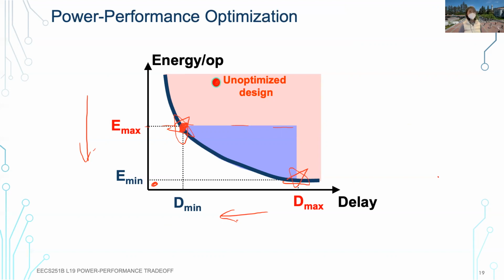For most hardware design, CPU architecture design, it's more like this. Let's say there's a particular energy envelope we want to hit. Let's find the minimum delay design that can actually achieve that energy. So in most designs, it's more like this. It's still pushing very aggressively on energy and minimizing delay, getting better performance. For this style of design, it's less showing up in processors, but showing up a lot when we need to interact with sensors. There's a particular rate that you need to hit, especially in a lot of microcontrollers.